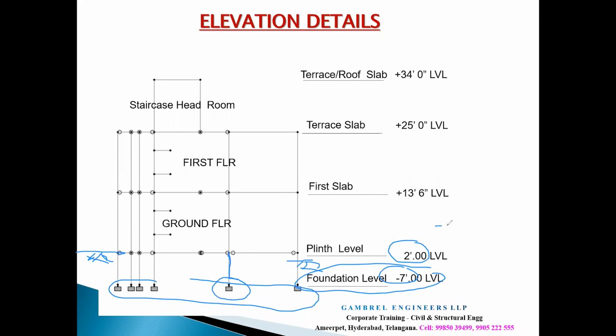For example, let me say it is a ground level. We always take the height of the building around 2 feet higher, because when rain comes, the stagnated water should not enter your home. If you don't wish to allow this rainwater stagnation, obviously your floor level should be a little higher than the ground level or road level, right? So that is why this should usually be 2 feet height. That is why we mentioned a plinth level of 2 feet here.